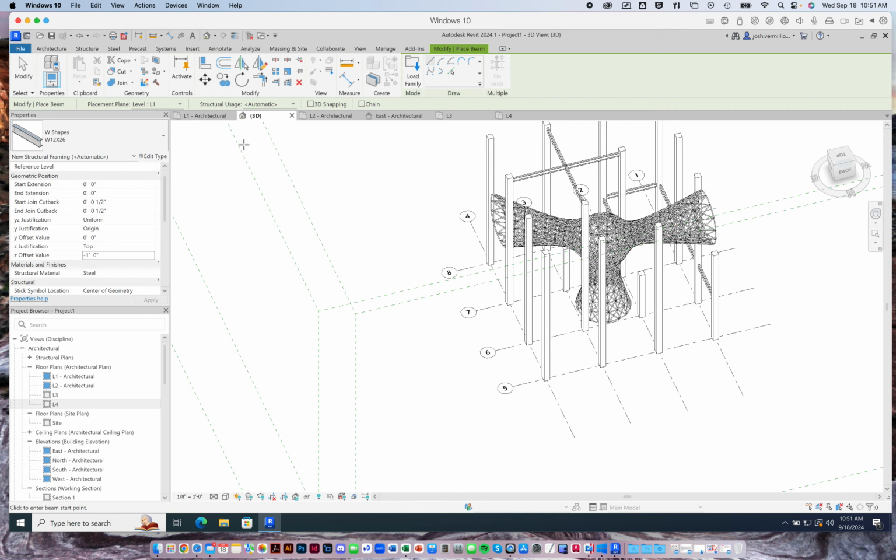So again, go back to your Rhino file, clean some things up, save a version out that only has the diagram geometry in it, right? Those struts and the lattice, right? The struts and nodes. Then you can open up Revit, import that in, start to establish the grid, and start to build a structural and architectural grid, right? With columns and beams.